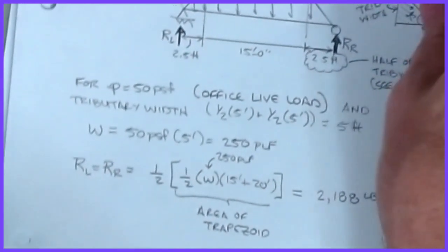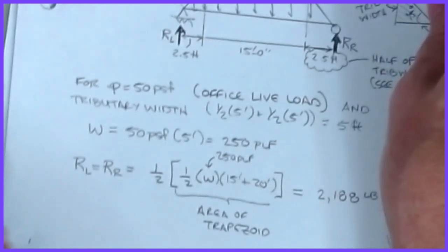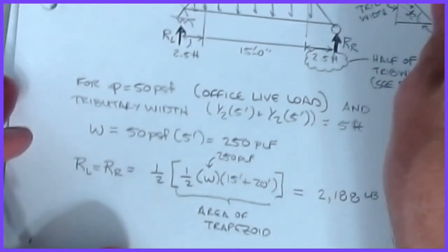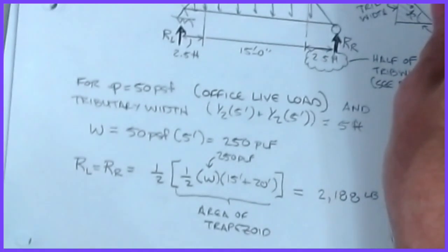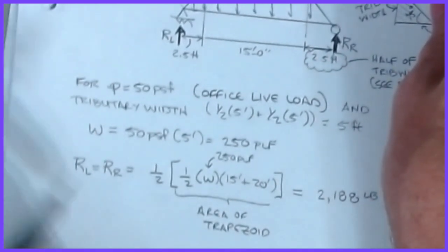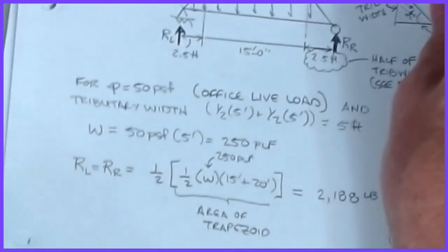One of the drawbacks of flush framing, though, is there's a lot more effort that goes into putting all that together most of the time. Okay, there's generally more connections, there's more bolts, or there's some extra additional welding that's needed. It's not just a gravity bearing type of connection as we saw on there.